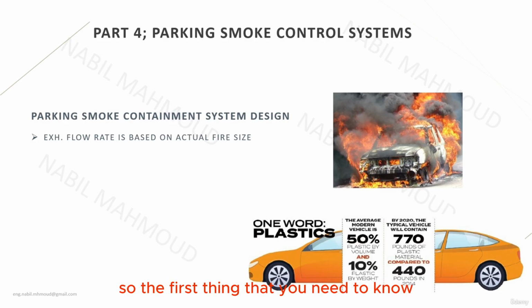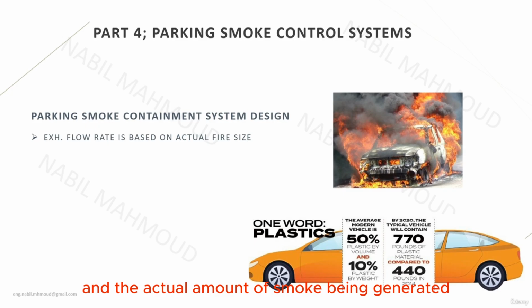So the first thing that you need to know is that the exhaust flow rate is based on the actual fire size, which means that the exhaust flow rate will vary if a sedan fire is proposed, compared to a truck, compared to a hydraulic parking with multiple cars stacked above each other. It varies in accordance with the actual load of the actual fire and the actual amount of smoke being generated from the fire that might happen.